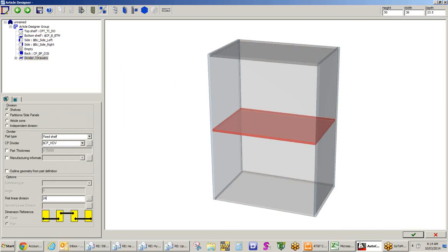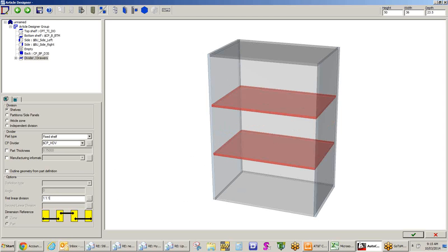I would also have the ability to put into it real numbers, such as 24:1 would tell it that 24 inches from the bottom is always where it's going to stay fixed, so it floats from the top. Or again, simple things like 1:24 IN, and it would be floating so that it would be locked from the top. So there's a lot of cool things that you can do with very basic formulas, and each one knows how to work within itself. I just gave it a 1:1:1 so that these would be always staying central to each other.